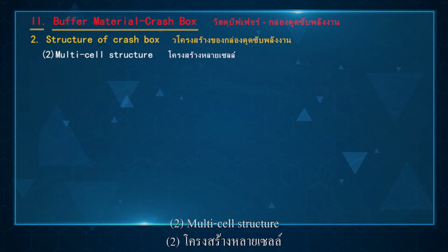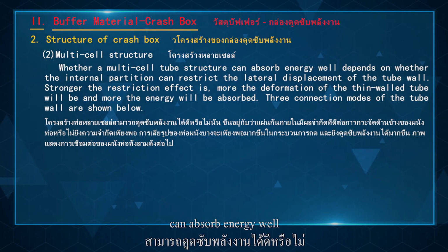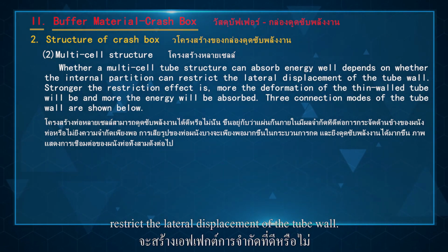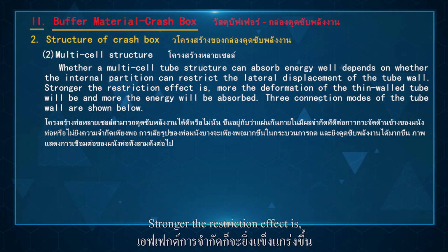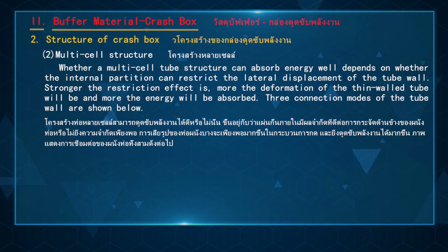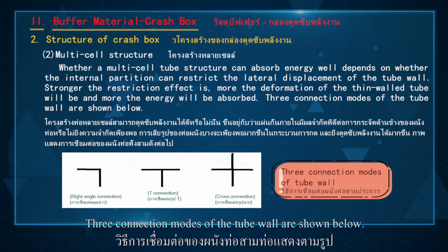2. Multi-cell structure. Whether a multi-cell tube structure can absorb energy well depends on whether the internal partition can restrict the lateral displacement of the tube wall. The stronger the restriction effect is, the more the thin wall tube will deform, and the more energy will be absorbed. 3 connection modes of the tube wall are shown below.